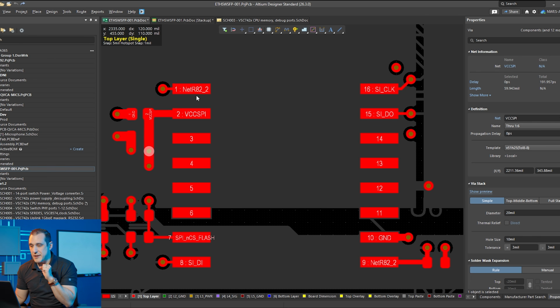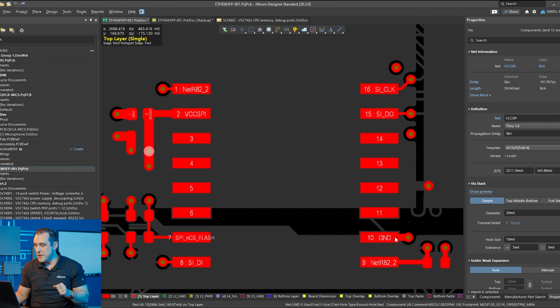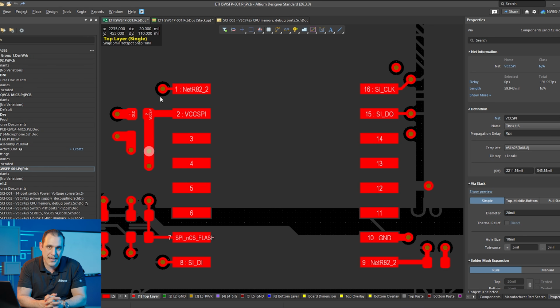So the question is, is it better to place these vias connecting to the planes rather than routing a trace from the ground pin on the capacitor all the way over here to this ground pin on the integrated circuit? Well, I think the answer is obviously yes. This is clearly better. It's better just from a placement and routing perspective. Why would you route a big trace all the way up here and take up all that space when you have a convenient connection to ground through a via, both on this pin and on this pin on the decoupling capacitor? So to me, it seems obvious that when you have the power pin and the ground pin placed far away from each other, the optimal way to do this in terms of convenience of routing is to just use vias to connect back to the plane.